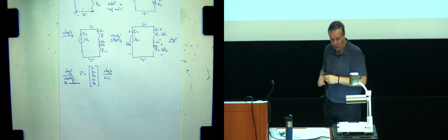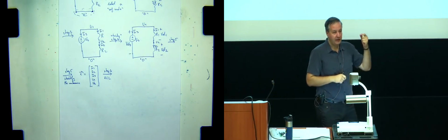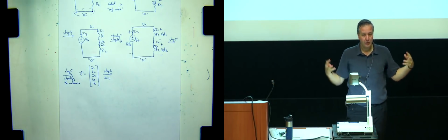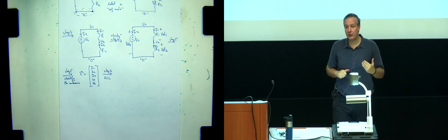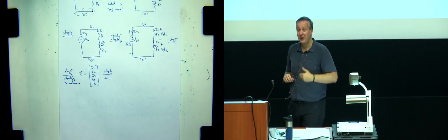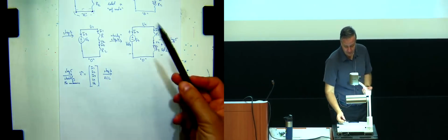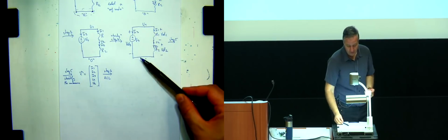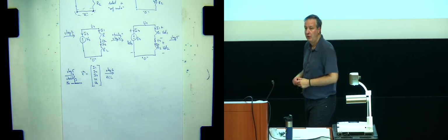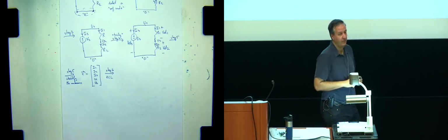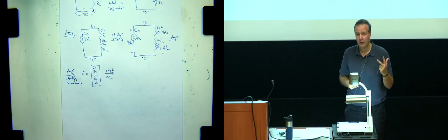If we're doing Kirchhoff's current law, we have to identify junctions on which we see how the currents sum together, and we need to identify linearly independent equations. So if I have in this circuit node 1, the reference node, and node 2, how many linearly independent equations can I write? I have 3 nodes.